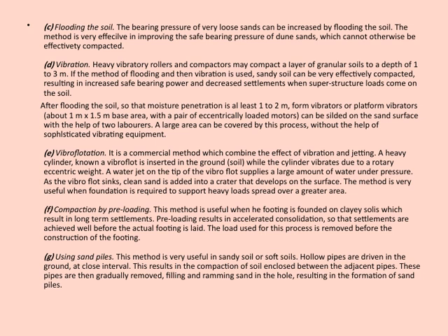The equipment involves using vibrators or platform vibrators, which typically have about a 1 by 1.5 meter base area with eccentrically loaded motors. By sliding these on the sand surface, assisted by 2 laborers, large areas can be treated without sophisticated machinery. It's a practical, cost-effective approach.